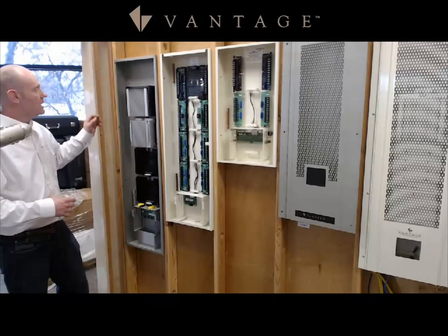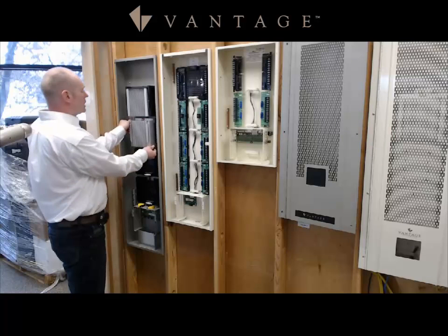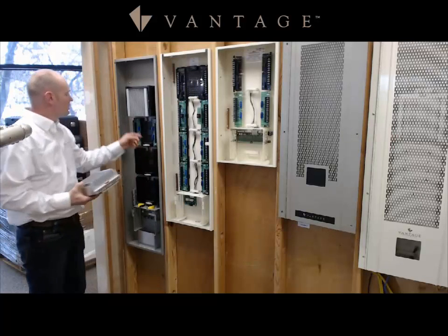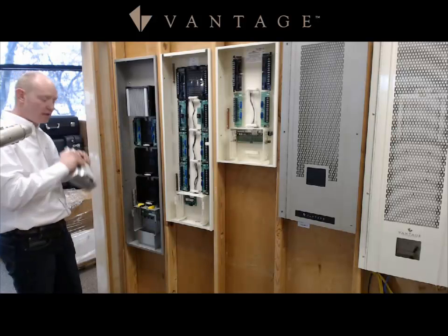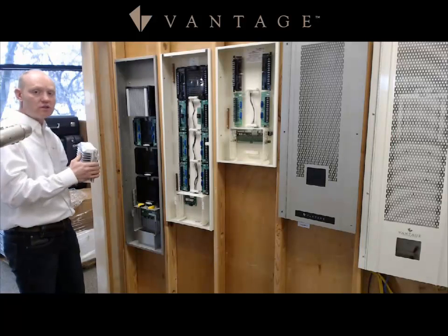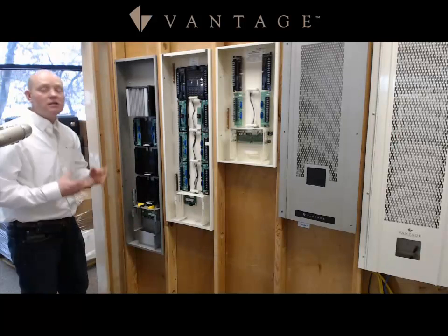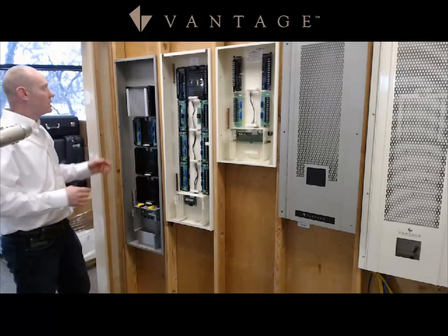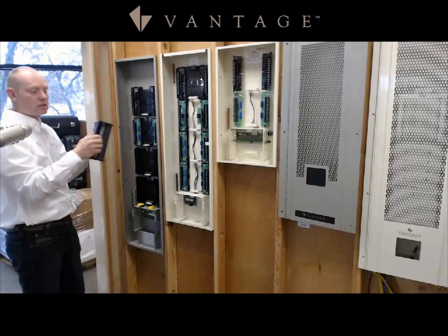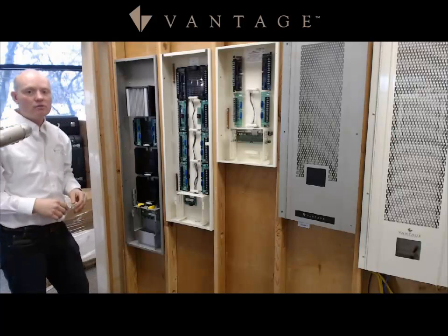As well as, and we've had this for some time, the plug and play capabilities. Breakers turned off, flip the little tabs, and you can pull those out, and that's the dimmer modules, the reverse phase dimmer modules, and relay modules with the green boards. An additional feature with the new standard dimmer module is we've actually got latches on the sides now that you just grab and disconnect, and very easily pull that out and set it back in.